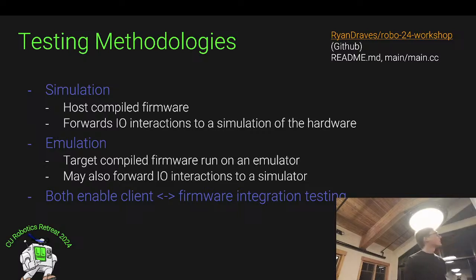Another way you might do it is to compile for the target, but then run it through an emulator. Emulators are typically expensive, unless someone is really nice to you and gives you an open source one. And typically, they'll also do the same thing for these I/O interactions, so you can write tests and make sure that the pins toggled as expected or whatnot. But both these methodologies will enable you to do full client and firmware integration testing.